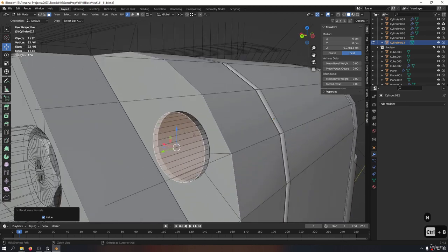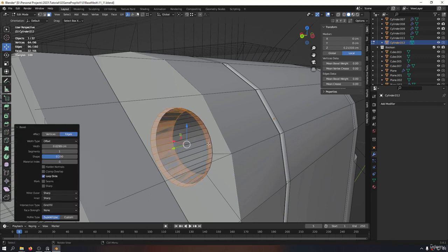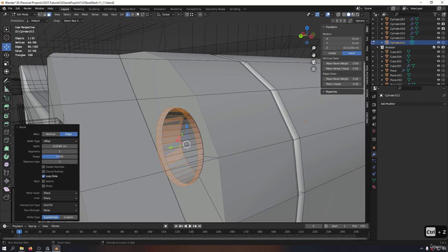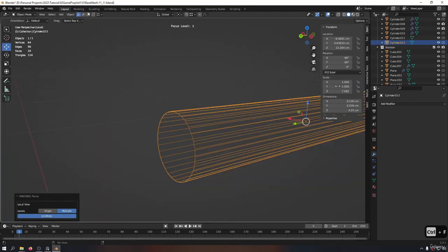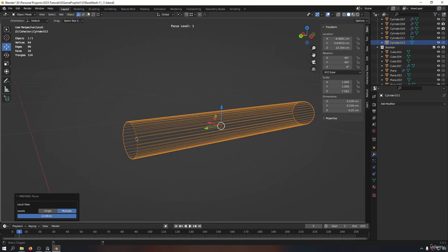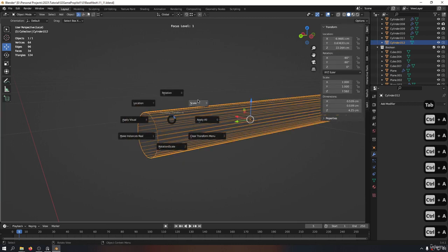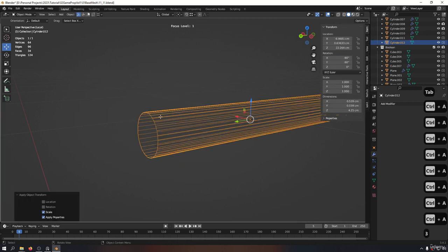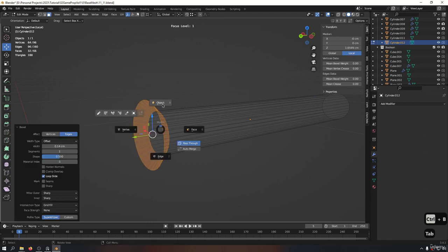And then I'm taking this, Control B to add a small bevel to make the edges shine a little bit more. Okay. But before that, let's go and apply the scale on this one, because without actually having the scale applied, it's not doing a good bevel. So let's do a bevel to see what that does. Control B. Now you see it's not actually doing what we wanted. But if I go and apply the scale and go try to bevel, see now this is doing perfectly what we wanted.